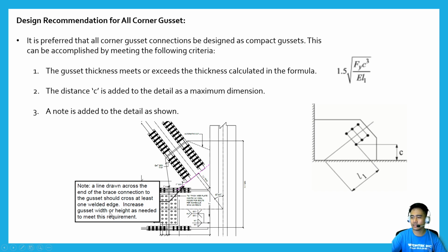Increase gusset width or height as needed to meet this requirement. Okay.